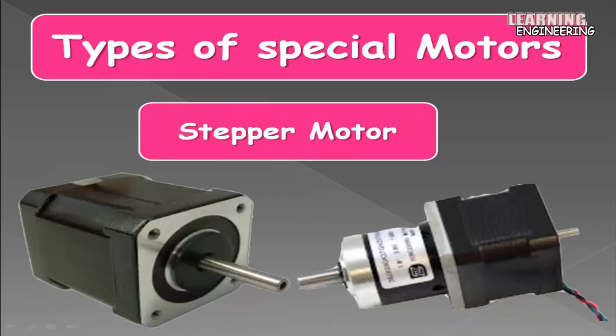Types of special electric motors. There are four types of special motors explained below. Stepper motors. Stepper motors are DC motors that move in discrete steps. They have multiple coils that are organized in groups called phases. By energizing each phase in sequence, the motor will rotate one step at a time. With computer-controlled stepping, you can achieve very precise positioning and speed control.